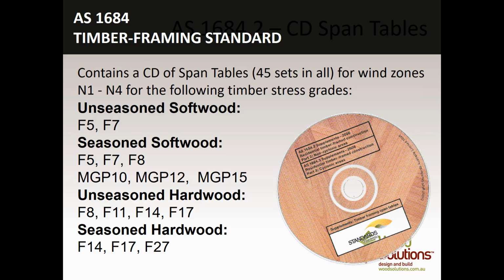You'll be using seasoned softwood F7 a lot for a lot of your external timbers, so for all of your veranda beams, pergola constructions, fascias, barge boards.